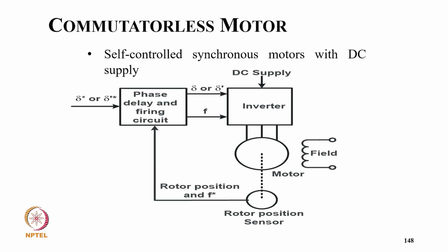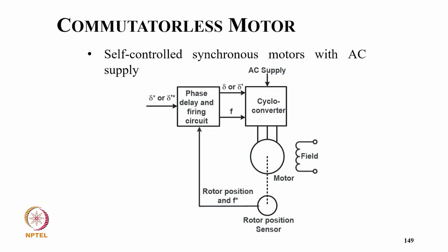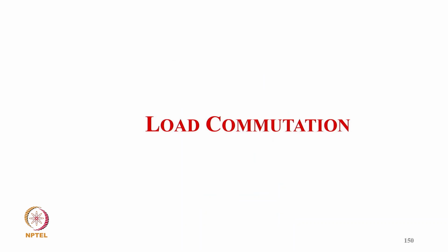Typically we have a separate field control for above base speed, and we have power angle control with position feedback. We have angle control and frequency control for this self-control synchronous motor. For the self-controlled synchronous motor with cycloconverters, we have a similar concept.